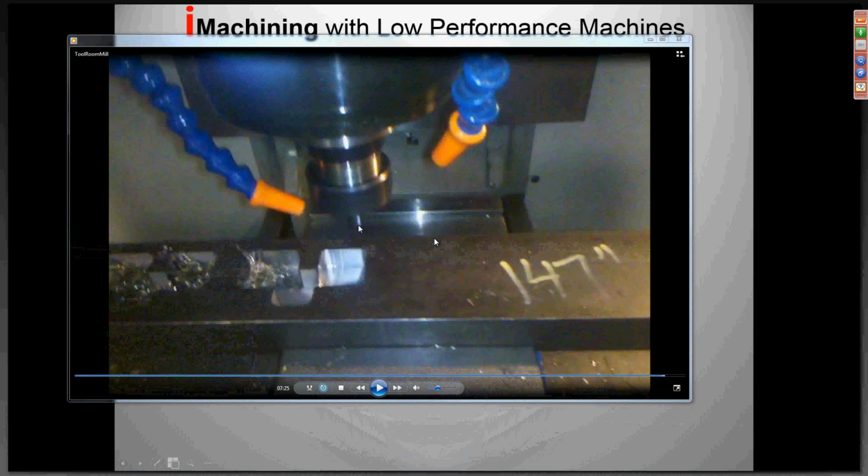and when we pulled this tool out and looked at it, I'm not kidding you, under I think it was a 3 or a 4X eye loop, you could not see that that tool was worn. There was not even scuffing of the coating on that tool. Now, to prove them out, I ran 3 more pockets on this bar with that same tool, each one of them in 7 minutes and 25 seconds, and at the end of that fourth, if you really studied it hard, you could see some tiny scuff marks in the coating, but that tool was dead sharp.